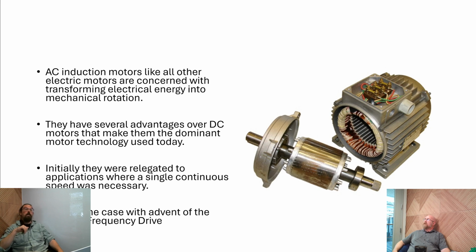If we look at this from a components perspective real quick, the stator is essentially the housing for the motor in this case, and the rotor is the thing that we see pulled out of the motor. Unlike a permanent magnet DC or a field winding DC motor, there are no wires going to the middle, which makes it extremely cheap to produce. It also makes this very mechanically reliable. There's almost no maintenance on these motors.